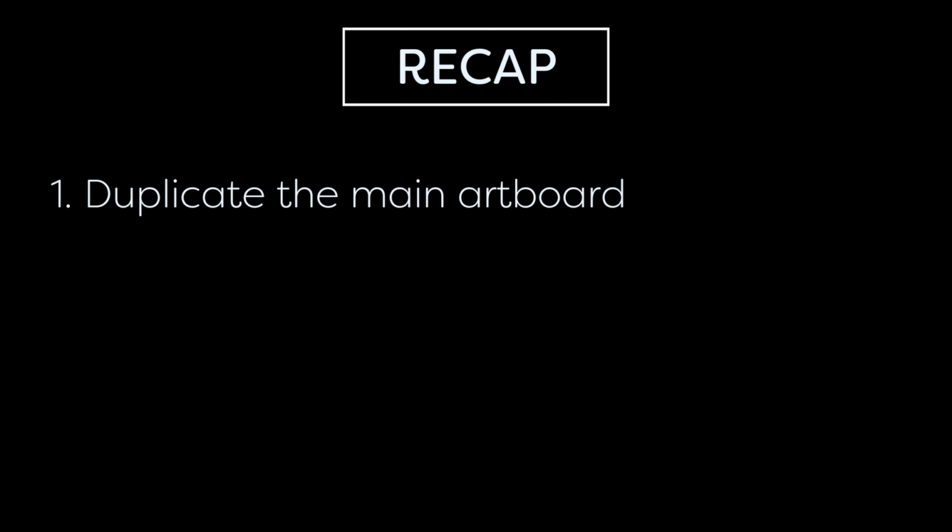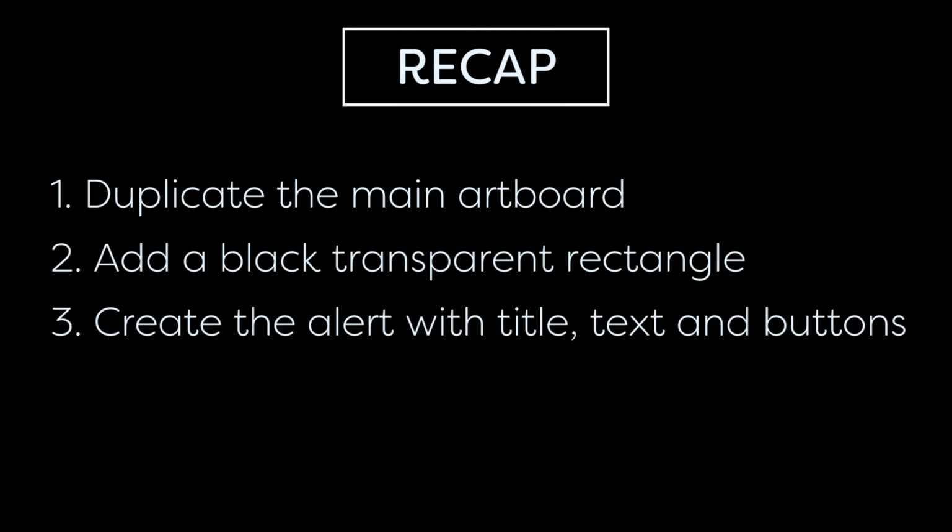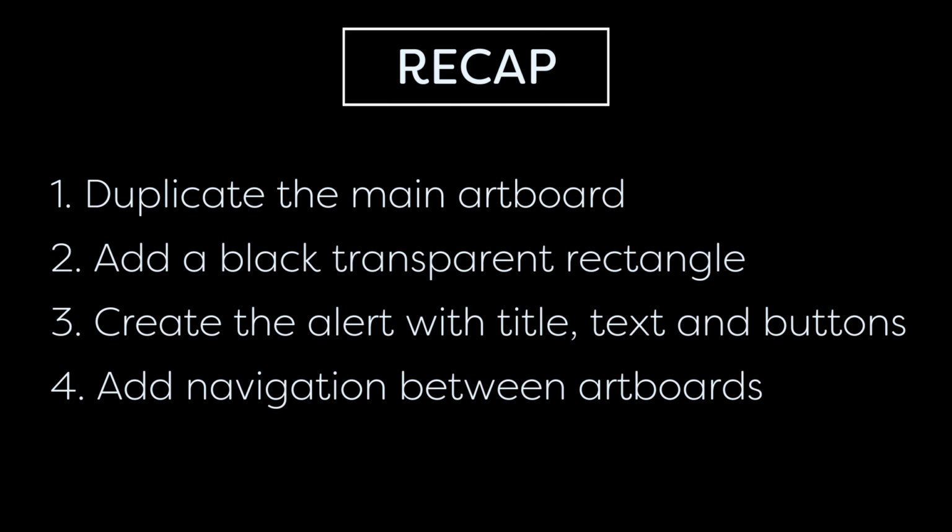Recap. Duplicate the artboard that you're going to be using to display the alert. Add a black transparent rectangle so you can unfocus the background. Create an alert with title, text, and buttons. Add a navigation with dissolve transition between artboards.